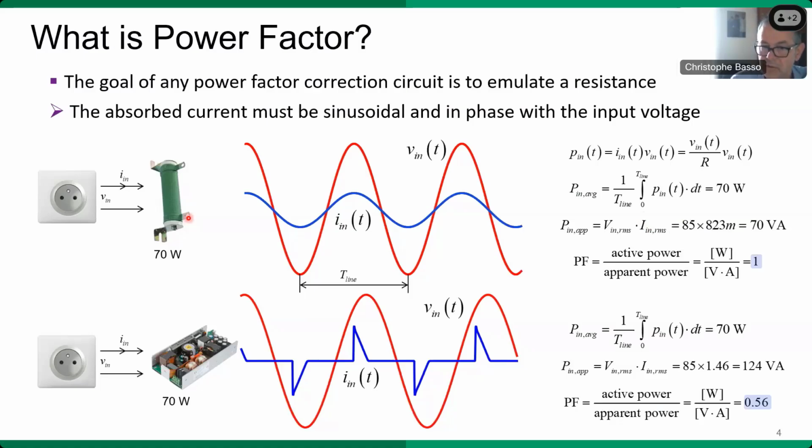The active or average power, P, is expressed in watts and characterizes the physical work that is being executed, like powering an incandescent light bulb or a big motor. The reactive power, Q, is expressed in volt amperes reactive, and it corresponds to a part brought by capacitive or inductive components of the load. It does not exactly participate to the active power, but it increases the circulating RMS current.